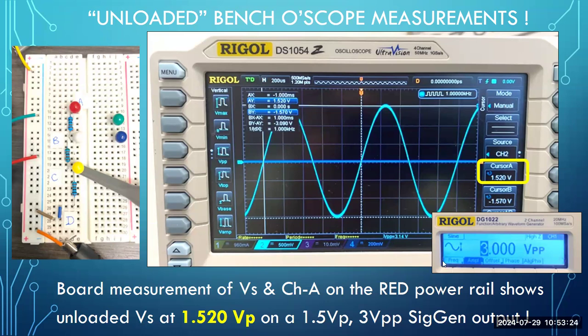Bonus is always good. So the board measurement is of the source, and the board measurements channel A of the oscilloscope. Both of these are attached to the red power rail, and it shows I have an unloaded circuit voltage source on the board of 1.520 volt peak against a 1.5 volt peak signal generator output. Now, we're going to load this and see what happens next.